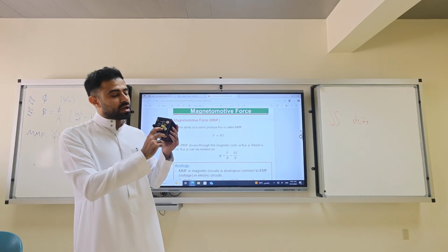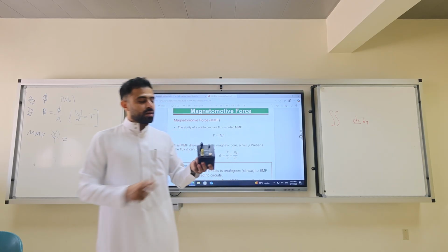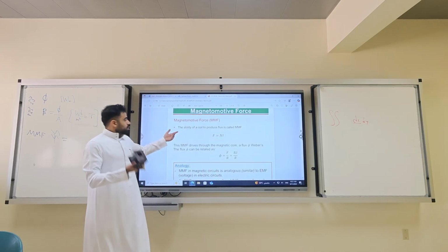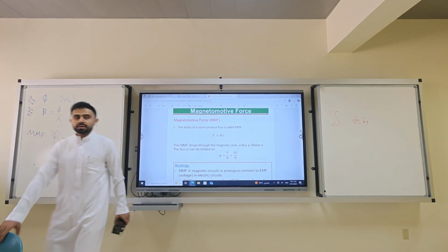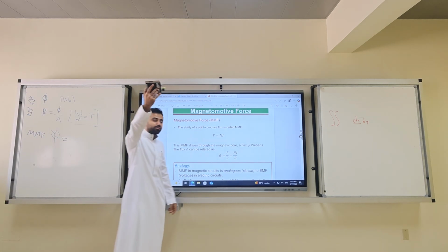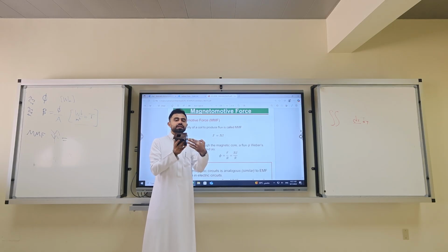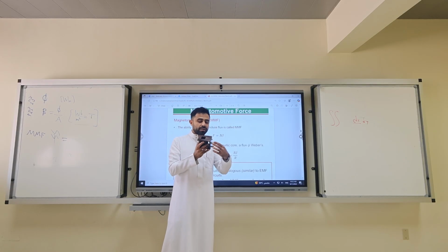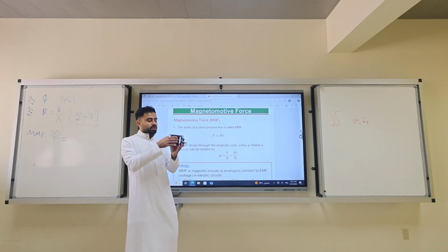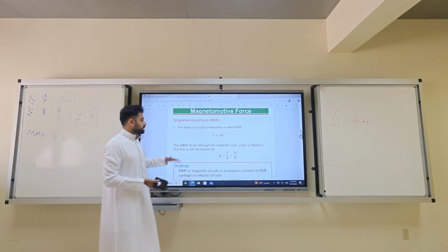He's telling you what is the wire. He even tells you the name of the wire. He's telling you the number of turns. You have to calculate it. So this is what? The ability of these coils to produce flux is called MMF, and it's related to N. What is N here? 400. What is I? Whatever we apply, I don't know. Maybe we apply 110 RMS, which is 110 times square root of 2 peak. So it would change. But let's get the RMS because we love RMS. What will happen here is to increase the ability to produce flux, increase the number of turns or increase the current.